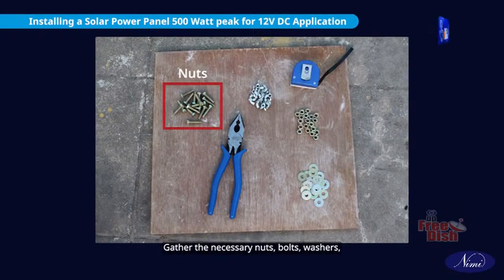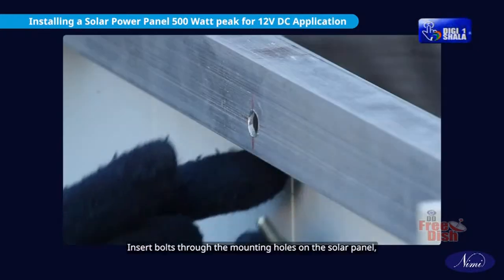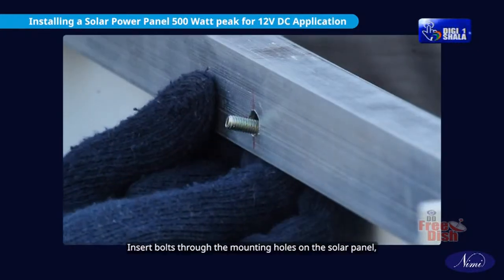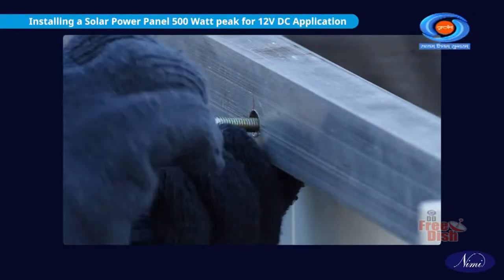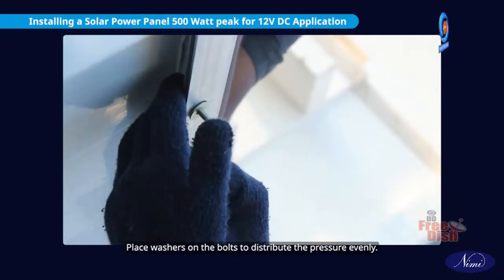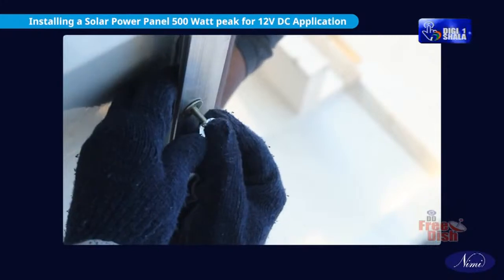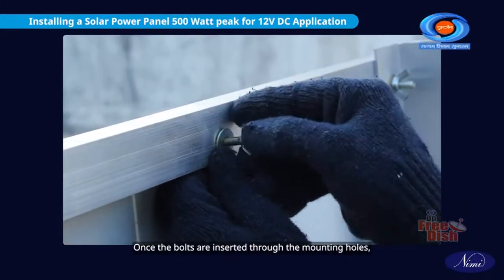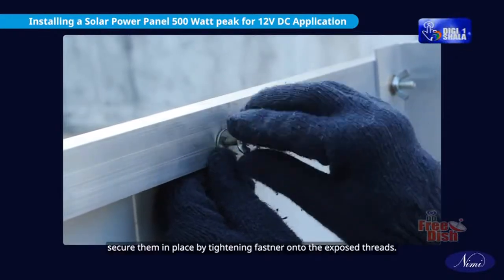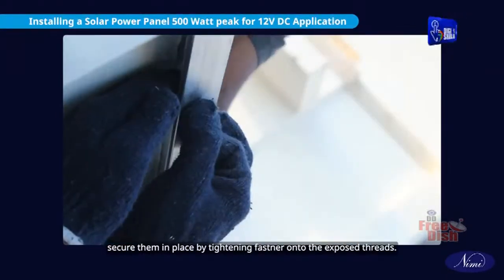Gather the necessary nuts, bolts, washers, and any other hardware required for mounting the solar panel. Insert bolts through the mounting holes on the solar panel, starting from the underside of the panel. Place washers on the bolts to distribute the pressure evenly. Once the bolts are inserted through the mounting holes, secure them in place by tightening fasteners onto the exposed threads.